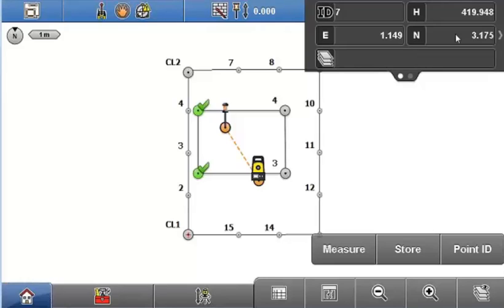So often the foreman on site knows exactly how much from his height benchmark, from the 420.5, he needs to dig down. So he can monitor here and know, let's say, from that benchmark I need to go down 3 meters, so he would end up at 417. So he needs to know, okay, from here I need to go down a bit further.